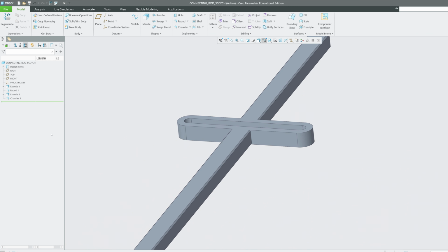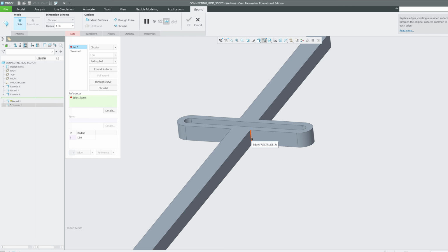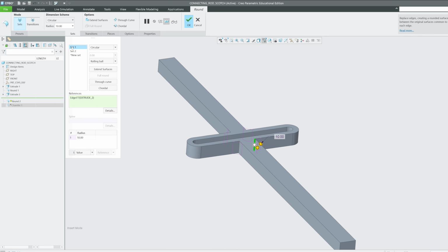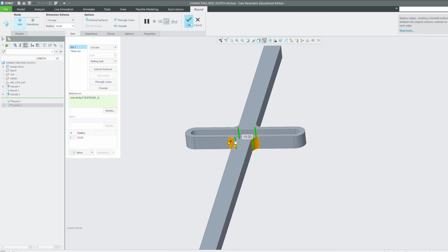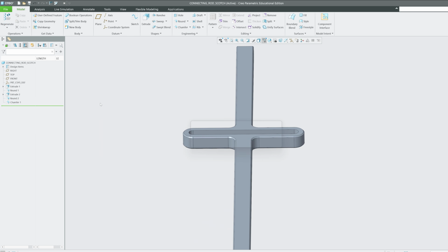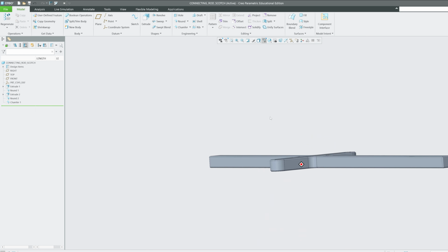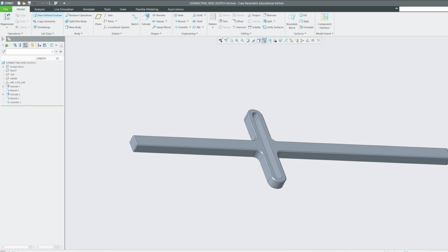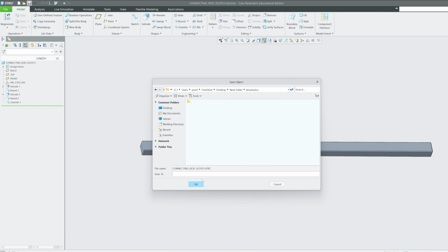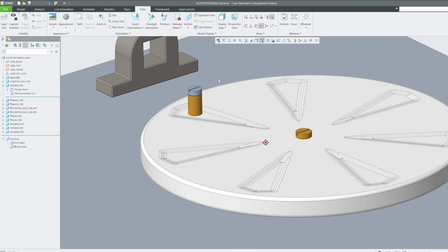Now all right, before chamfer, I think if I add round here, then that would be even awesome. Let's make it a round of 10 mm. Yeah, can delete this one actually. Now if I add chamfer, it will go like this. Yep, that's exactly what I wanted. And yeah, so let's save this part and close this.